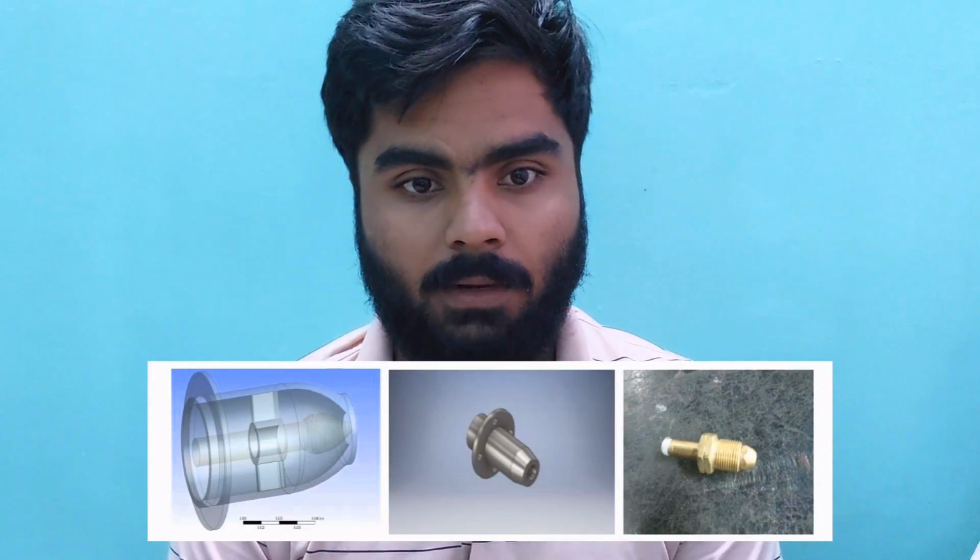Typically, these buckets are divided into two sections, so they are able to deflect water from the oncoming jet. A Pelton wheel also has a cutaway on the lower lip of the bucket, which allows a subsequent bucket to move ahead before it stops the water jet that moved the previous bucket. As a result, the bucket enters the water jet more smoothly.